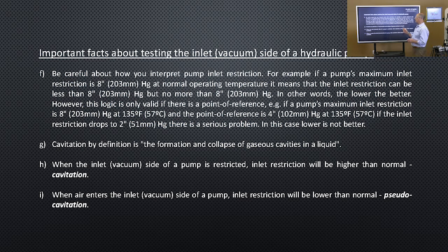Cavitation, by definition, is the formation and collapse of gaseous cavities in a liquid. Again, we demonstrated that. When we created a higher than normal inlet condition, we literally saw the dissolved air coming out of the oil, and we saw that once the implosion occurred in the pump, it went back into suspension. In other words, the gaseous cavity disappeared.